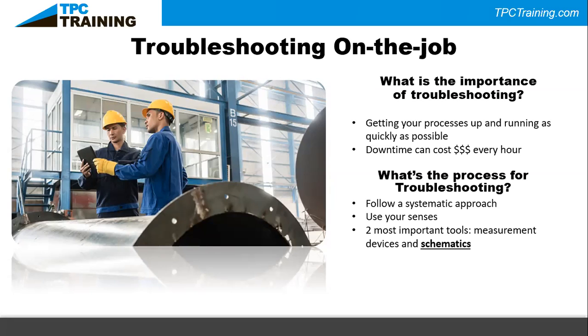The two most important tools that you have for troubleshooting after your senses start failing you, and let's say you can't see anything's wrong and you can't see anything's happening, then really measurement devices come into play during the troubleshooting process. If you're electrical troubleshooting, that means using a multimeter and those electrical schematics. If you're talking about mechanical troubleshooting, maybe you'll need to do some vibration analysis or some infrared testing or some displacement measurement to know what's happening on the mechanical side.